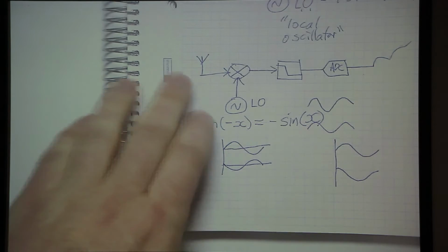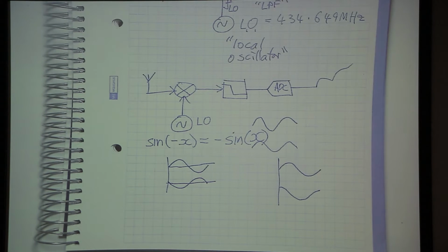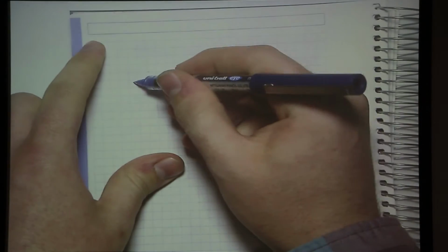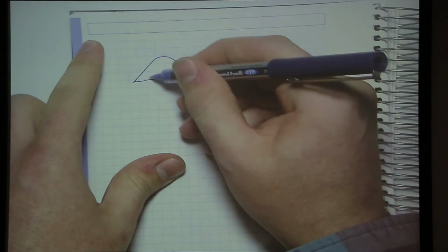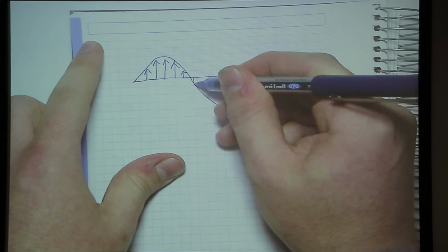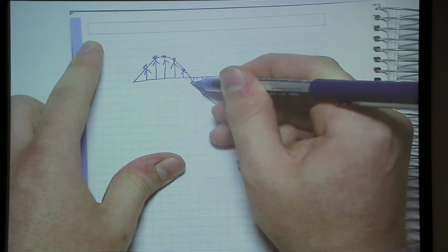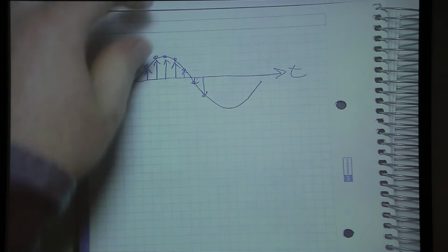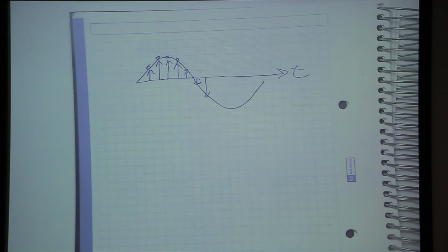So how can we really measure that? If we think back to what the ADC does, then at any moment in time, it records the analog voltage it sees. And we know that analog voltage is oscillating up and down. So really what we record is, if this is time, at several moments in time, we record the amplitude of the signal, and that's the number that we save. So, in a sense, we can know what the phase is at any moment in time by that amplitude. If it's a high number, then the phase is right here. If it's a low number, then the phase is this far across the cycle, 3/4 of the way through.